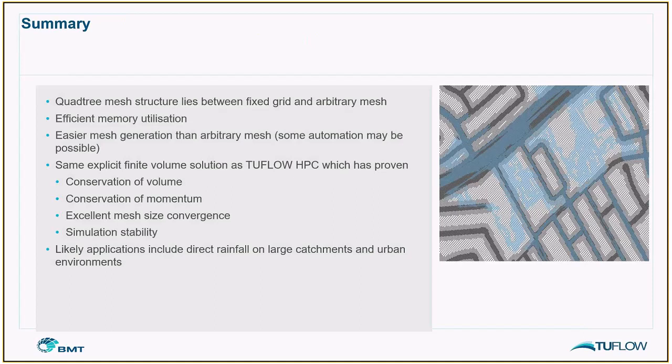So you said the model is conserving momentum, and that's quite interesting because not all urban models do conserve momentum, under the assumption that it's largely negated by frictional forces. Well, primarily the model itself is based on rural floodplains and channels. So it comes out of Australia, where a lot of the channels require the conservation of momentum, because it's quite important. You've got quite a few different forces going on there. Yeah, especially things like dam breaks. Exactly that. Yeah.